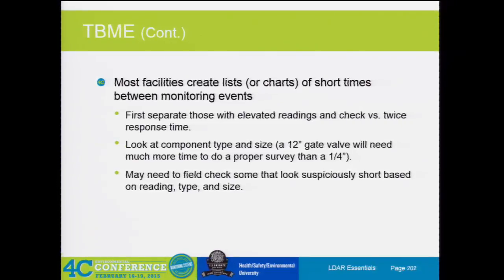What's going on here? Well, if you start seeing those same results, maybe it's time to go talk with that technician and give them a little more training. Maybe they don't understand. Well, you told me that you wanted me to sniff the packing, so I sniffed the packing. But he forgets that he's got all the bonnet and all the stem area. He only sniffs in this area because that's what he thinks. So I caught that by doing a little QA, QC. I'm getting better results, and away we go.